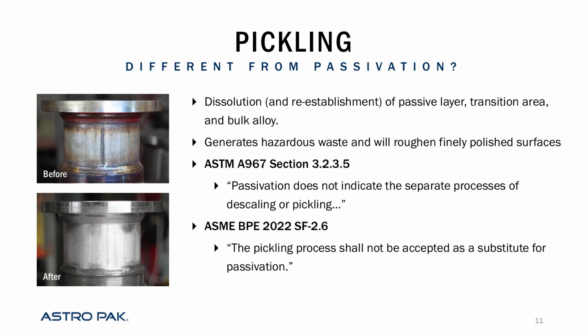As a result, a couple documents in the industry do a good job drawing a line between pickling and passivation. A967 is one of those, and then also the ASME BPE. That's a bioprocessing equipment standard, more in the pharmaceutical space. They do a really good job saying pickling is not a substitute for passivation. Language like this exists because if we're pickling, that's kind of our nuclear option. Of course, we're going to remove that contaminant iron that passivation targets. You are just removing so much else on that alloy surface, and you're not getting the same level of chromium enrichment. So that's why they're considered distinct from each other.